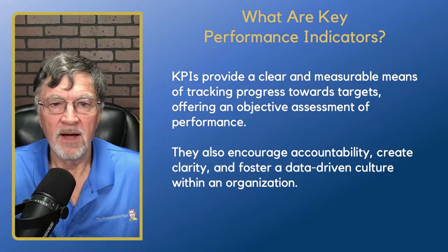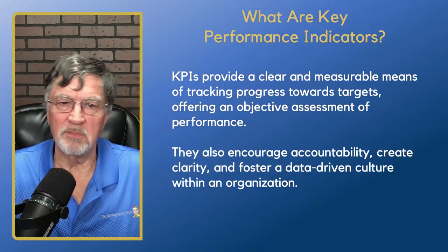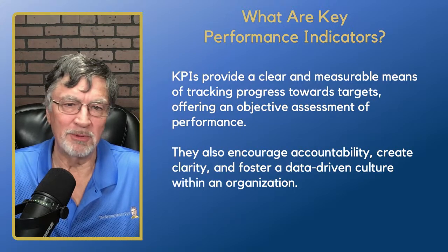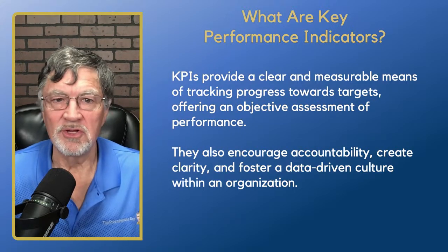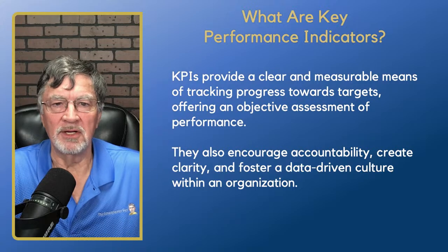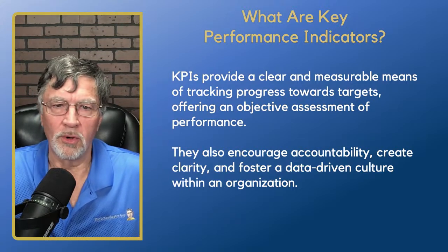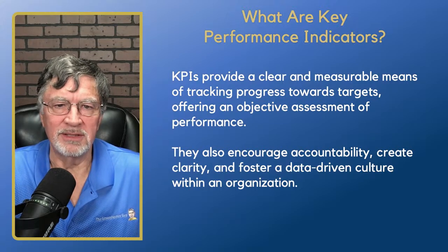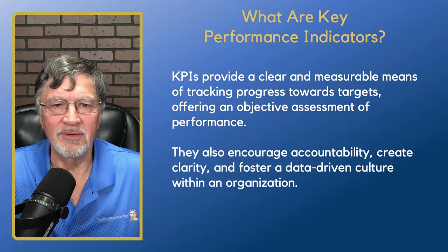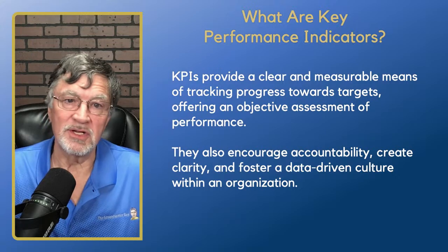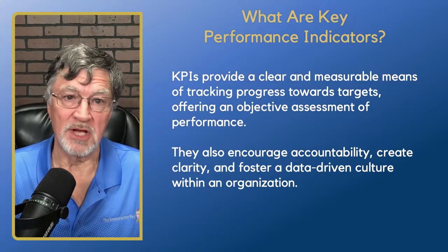I mean, as we always advise that people have an asset management plan and capital improvement plan, and this actually feeds into that, because if you're seeing a lot of water line breaks or leakage, then tracking that and seeing the trends may indicate your system is aging out.